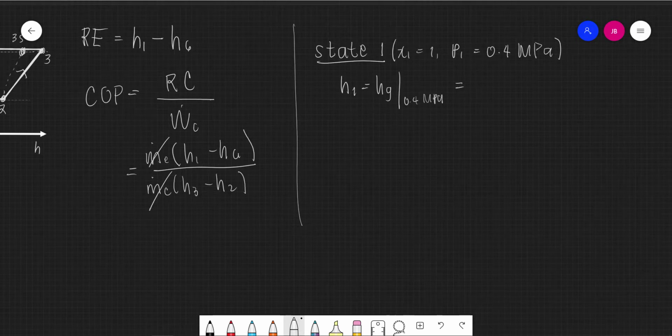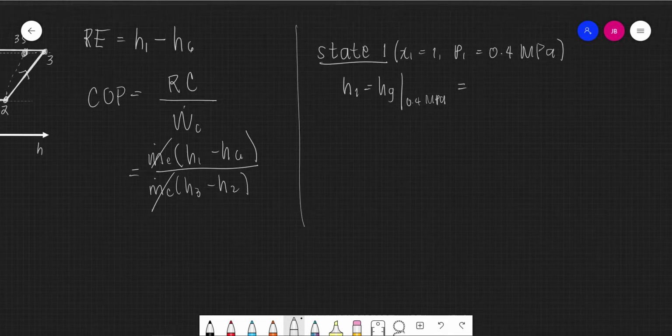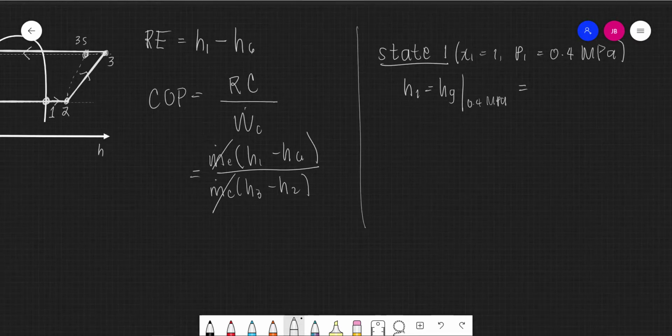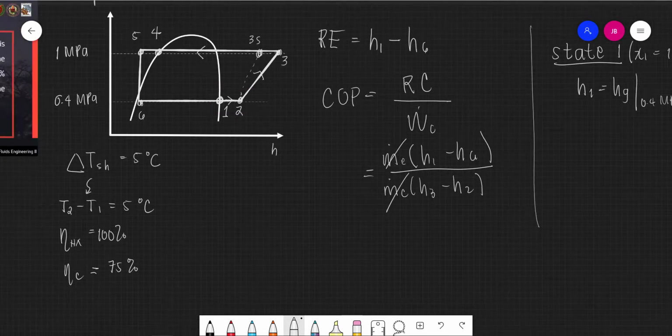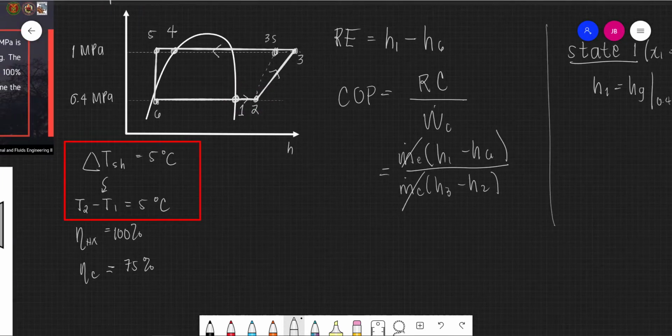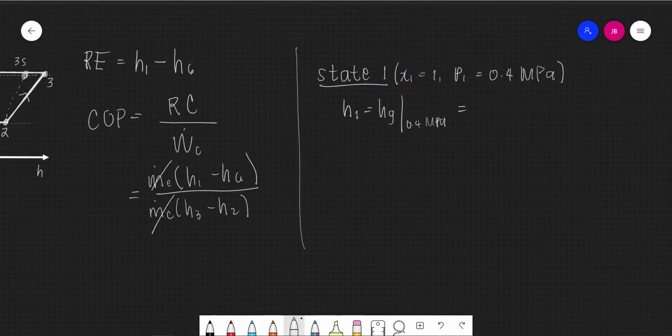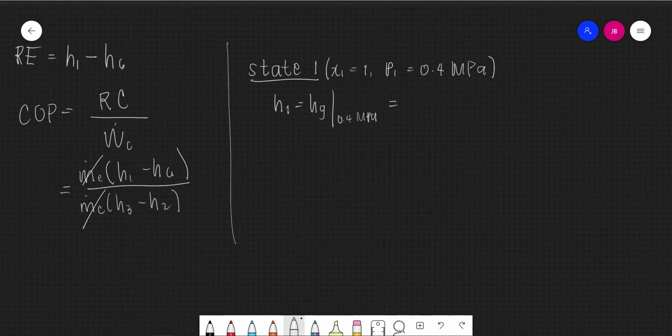In this case, we don't need to solve for the entropy. Bakit? Kasi kinakailangan lang naman natin yung entropy kapag meron tayong isentropic compression na kasunod or isentropic expansion also. But in this case, in order to jump to state 2 from state 1, ang kailangan natin ay temperature. Bakit? Kasi given yung ating degree superheating dito. So that is the purpose of our degree superheat. Okay, so instead of solving for the entropy, let's solve for the temperature instead.